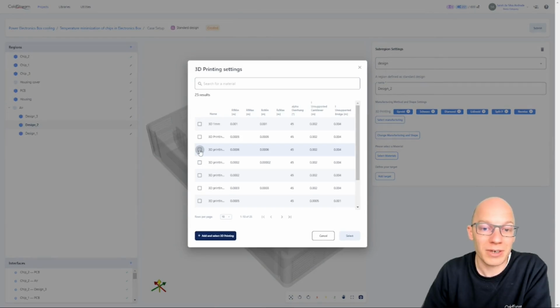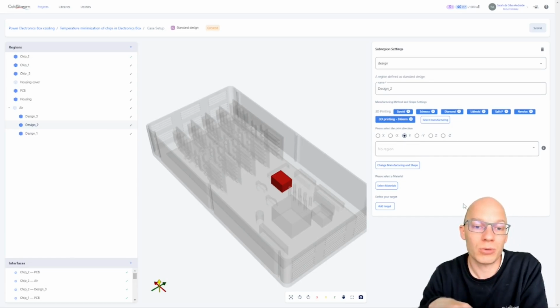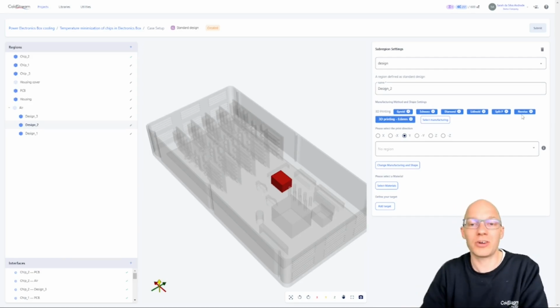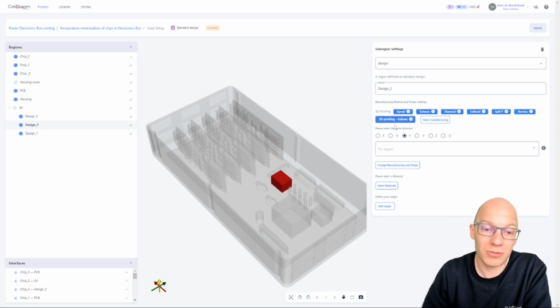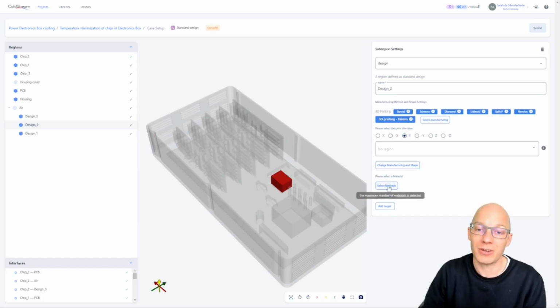then your manufacturing technique. I'm just going to randomly pick one. Voila, and a printing direction. Like this. And so what you basically have explained now to ColdStream is which shapes you want to evaluate. In this case, six basic shapes, base geometries, together with the manufacturing constraints. And within those set of constraints, ColdStream will search for the most optimal configuration.